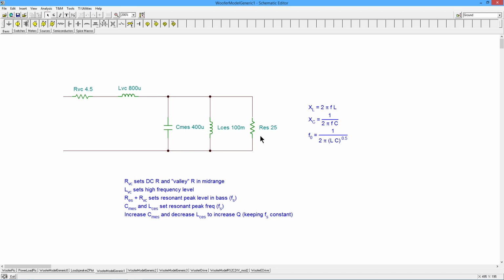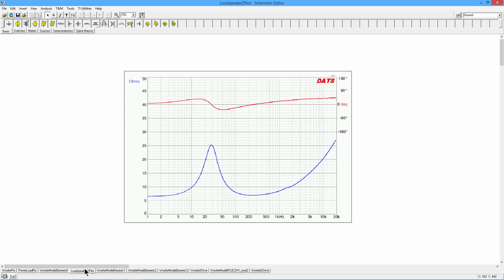And if you're familiar with AC circuit analysis, you will recognize that peak that we saw. This peak is sort of emblematic of a parallel resonant circuit, where the impedance peaks at a resonant frequency and falls off on either side. And that phase response would be typical of it. This inductive-capacitive transition with a 0 degree phase shift, in other words, purely resistive, right at the peak, all right?